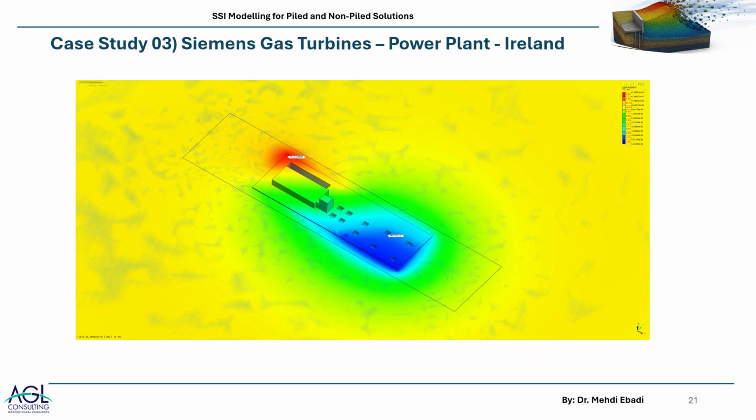For each load combination, we got settlements. There were criteria to check against. Angular distortion, we did the same. We had, for example, for this case, for accidental loads, 76 accidental load combinations. We did the settlement analysis, this angular distortion calculations, both checked. Okay, next step.